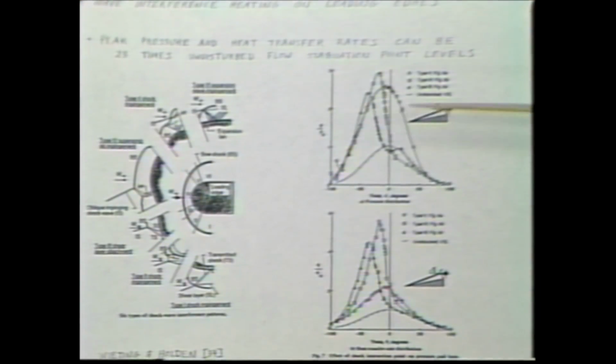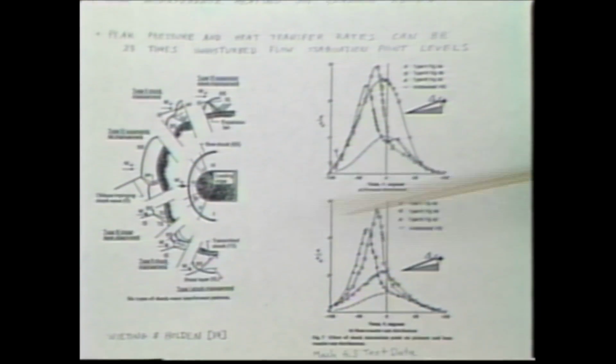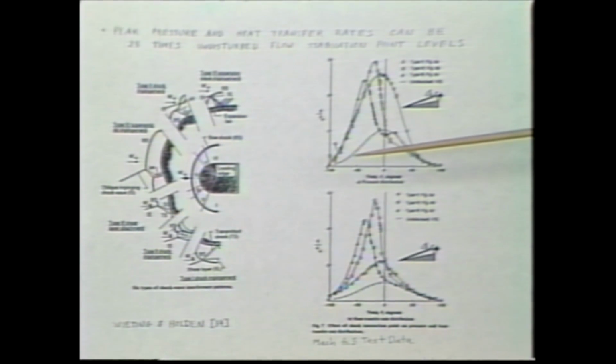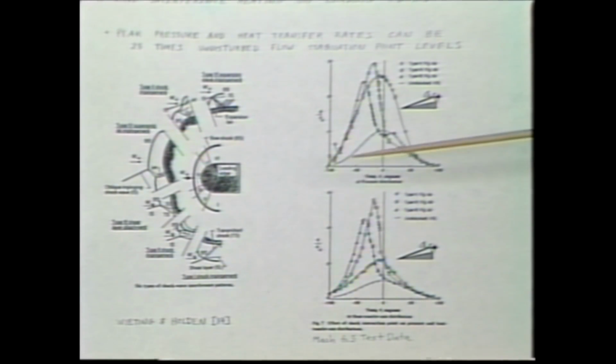Mark Lewis talked about this extensively, and even showed the same data, but just that issue of the cowl leading edge, I'll just add that our design is Mach 15 shock on lip. If we designed it so that the shock never went on the lip, you'd always be spilling flow and you'd have low performance. So at some point you will have to deal with the bow shock passing across, and ramp shocks crossing the leading edge and the heating associated with that.